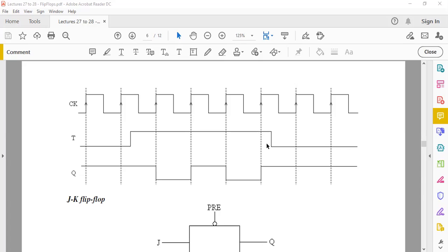And then now you can see your T pin has become low. So now rising edges do not cause any toggling in your output. This one is a bit more difficult to understand, but like I say, its name is toggling. So just to recap, whenever your pin T is high, your output Q will toggle state for every rising edge.